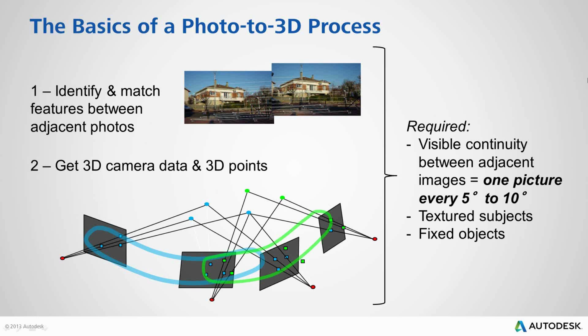Basically, if you move 360 around an object, being a house or a small object, whatever, please shoot at least 50 to 60 photos for one set if you want to completely make the 360 over it. In most projects, we'll end up with something like 100 to 200 photos. Don't expect a good result if you take only 5 or 12 pictures.